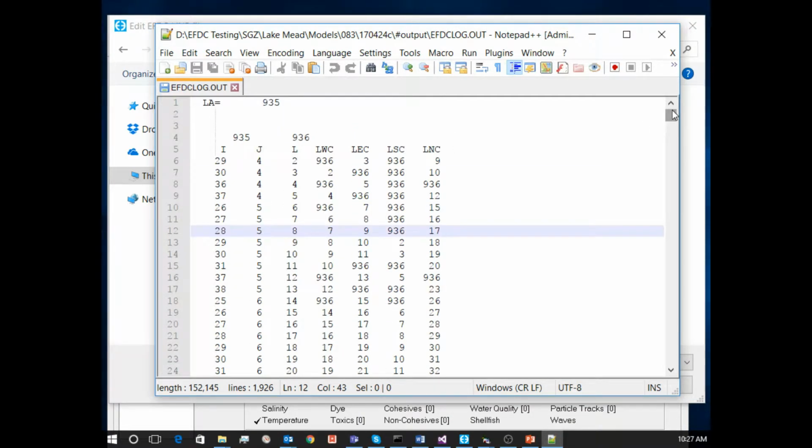This is actually new information: we no longer use I plus 1, I minus 1, or L minus 1, L plus 1 for dealing with your array index, because we now have north-south connectors and east-west connectors. Historically, EFDC has had north-south connectors for a long time, but now that we have east-west connectors, everything is an array. Every index is a lookup array.